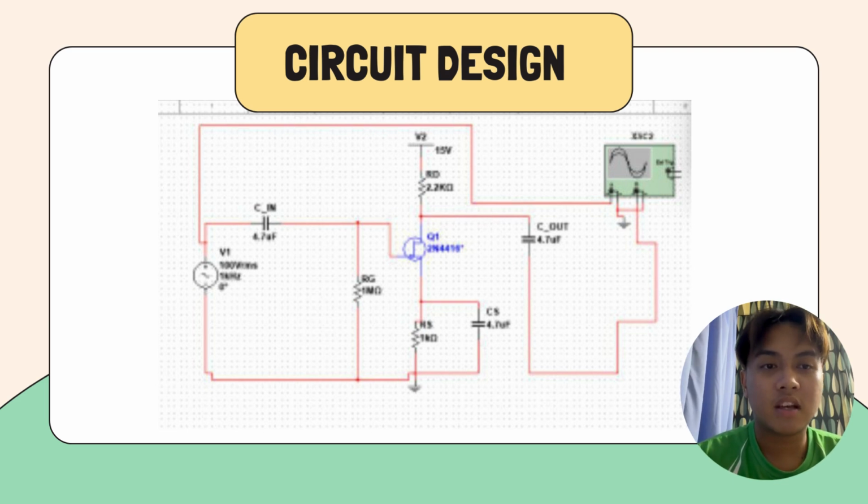For the drain resistor RD, this is set to 2.2 kilo ohm. It is connected to the 15V VDD supply. RD is critical because it converts the JFET's current changes into the output voltage signal we want to amplify.